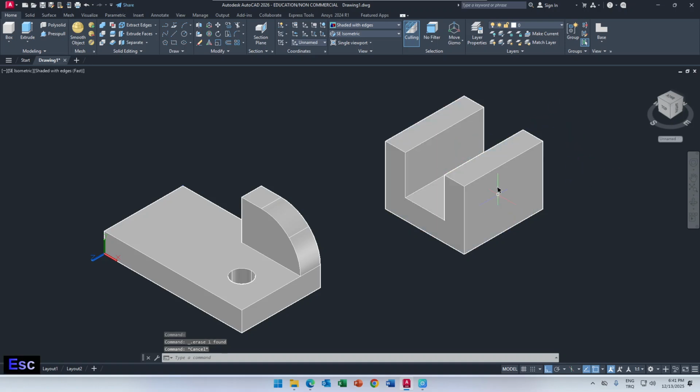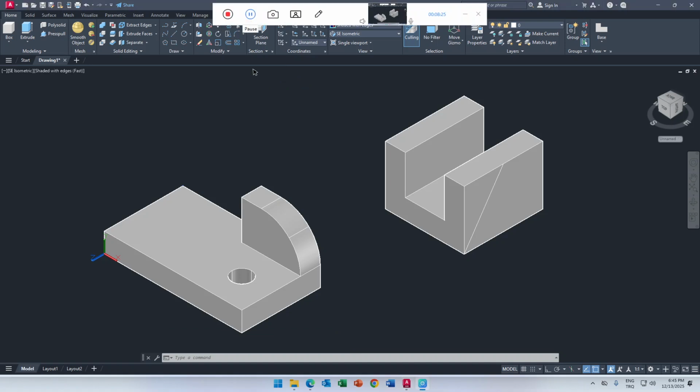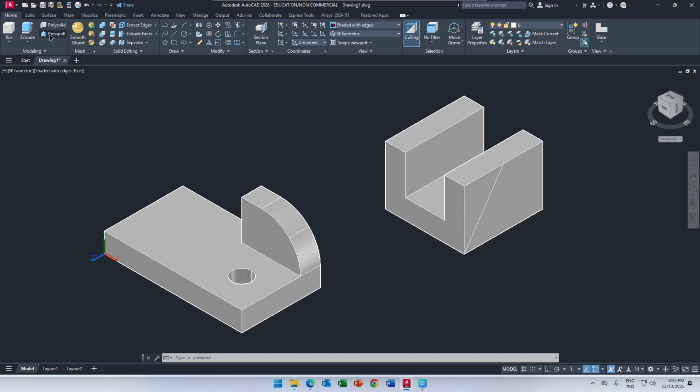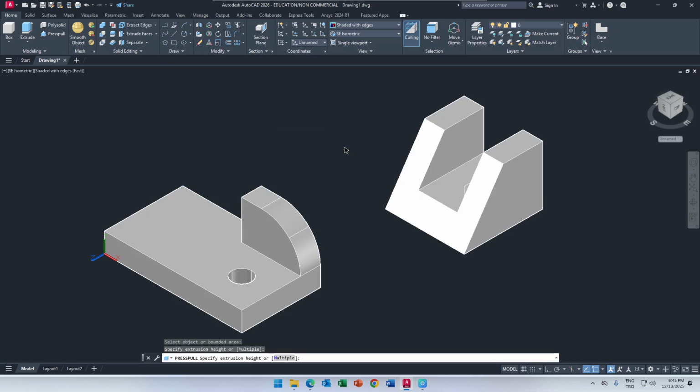So I want to cut here too by creating a rectangle. Click the polyline again, come to the face. You want to draw, click, and go right with, let's say, 20. Then turn ortho mode off, click, and then you can press pull and select the triangle, and now you have tapered the face.